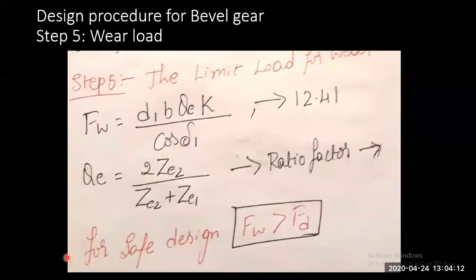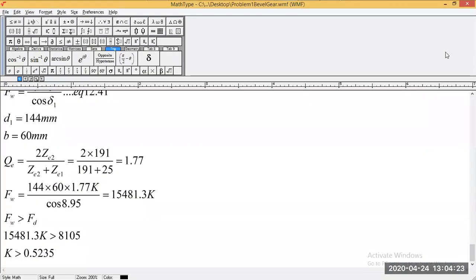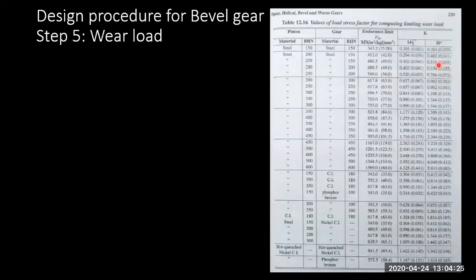For this, let's see what is the recommended hardness. So for the 20-degree K value, 0.5235, it's closer to this value here for 20-degree, and the combination of steel there is 250 and 150. So that is the recommended hardness here.